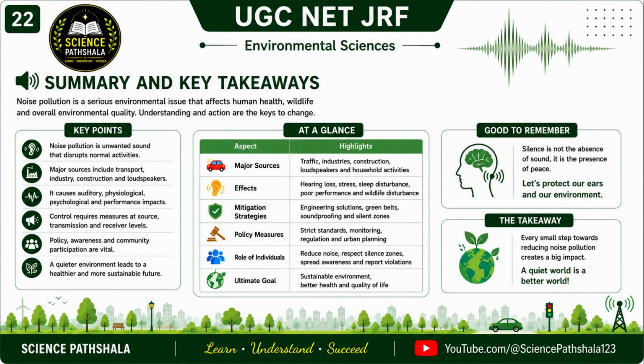Now let us summarize the important concepts discussed in this lecture. In this complete session, we studied the fundamentals of noise pollution along with the important numerical and conceptual topics relevant for competitive exams. Firstly, we understood the decibel scale and its logarithmic nature. We learned that sound levels cannot be added or subtracted using simple arithmetic methods because decibel is a logarithmic unit. Then we discussed important formulas related to sound pressure level, sound intensity level, and logarithmic sound calculations.